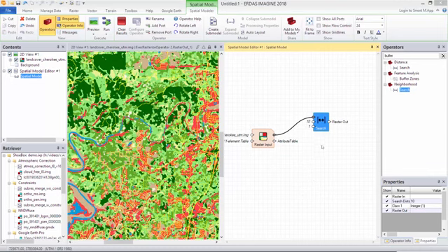And the search function is going to give us basically an output with effectively 12 classes, 0 through 11. The class value 0 from the search will indicate no distance from the water class, i.e. water classes themselves will be the 0. Then you'll have DN values of 1 through 10 indicating the distance from that water class, and then 11 is everything beyond the specified distance. And obviously for our criteria of being within 150 meters of water class, we need to select everything that's less than or equal to the 10 value.